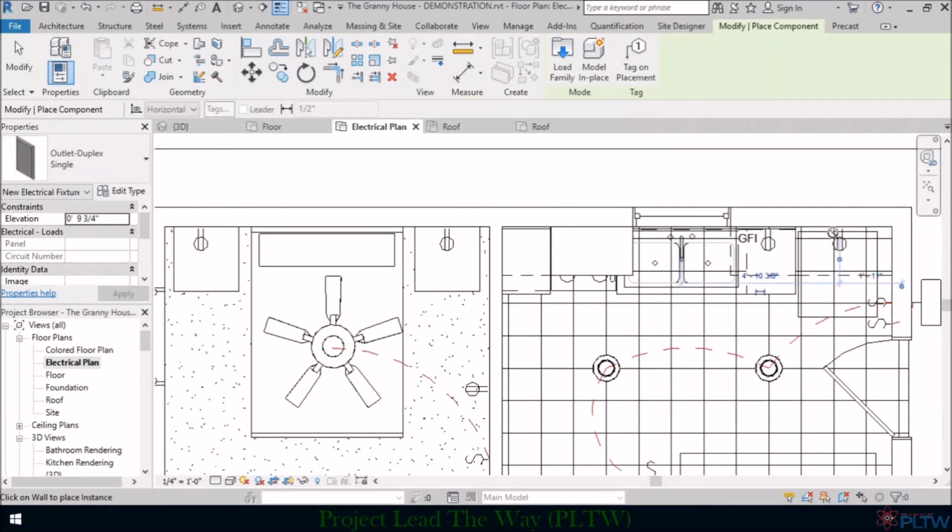And you may say, well, why would you do that? Well, the way a GFI outlet works, if water happens to exist near this outlet and trips this and causes the whole system to break off, if that happens here, a person's going to have to pull this whole refrigerator out and push the button on that GFI outlet to have it reset. So anytime a GFI outlet trips, there is a button on that outlet that they will actually have to push to make sure it gets reset. So that's why we use a regular outlet here.